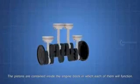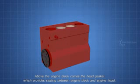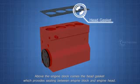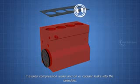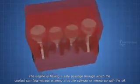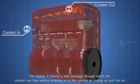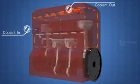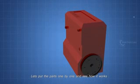The pistons are contained inside the engine block, in which each of them will function. Above the engine block comes the head gasket, which provides sealing between engine block and engine head. It avoids compression leaks and oil or coolant leaks into the cylinders. Above that comes the engine head. The engine has a safe passage through which the coolant can flow without entering into the cylinder or mixing up with the oil. This passage is known as the water jacket. Let's put the parts in one by one, and see how it works.